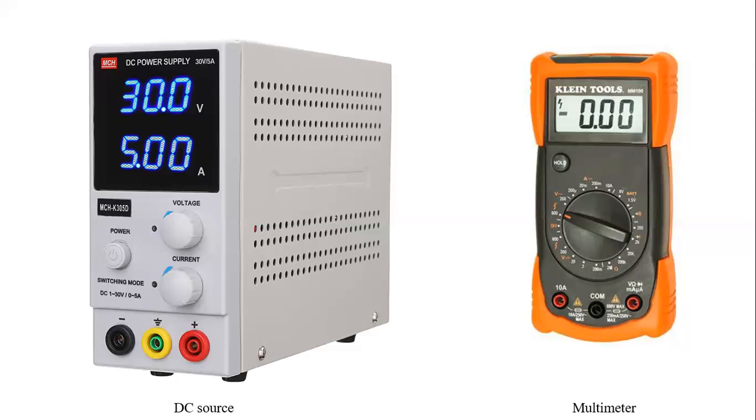There are three connecting knobs. One is 10 ampere, one is common, and another is for voltage. The common one will always be used. Now we can connect either the 10 ampere one if we have to measure a very high amount of current, or the voltage one if we have to measure a low amount of current and some voltages or resistances. Then we have to connect the other lead in the other port.